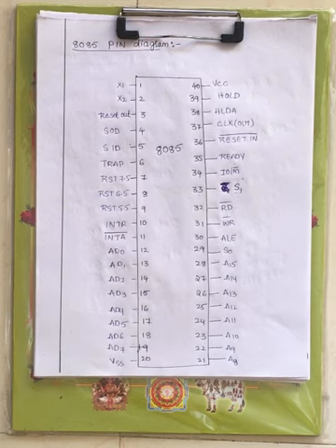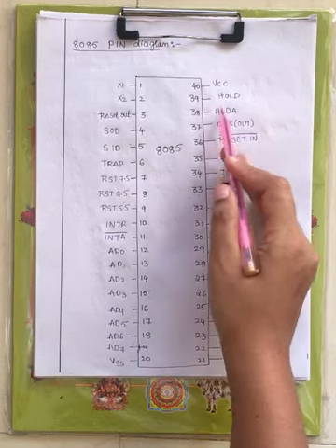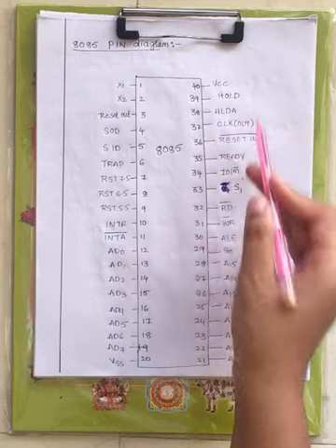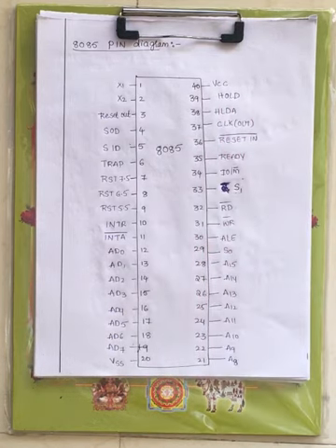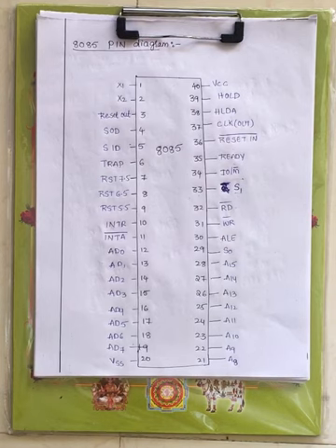Now if any other devices want the system clock, that can be taken through this clock out. Next you have VCC. At the 38th pin you have HLDA, the hold acknowledgement signal. HLDA stands for hold acknowledgement signal. Now at the 39th pin you have the hold signal. What is meant by the hold signal we will see later.